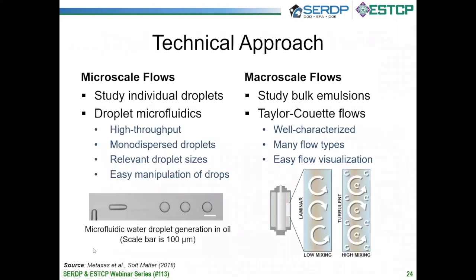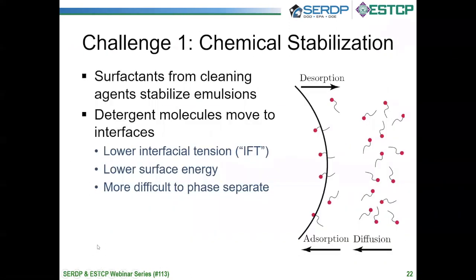So the first challenge, like I was saying, is that they're highly chemically stabilized. These waters will pick up detergents like deck cleaners, and soaps from personal care products, and these cleaners and soaps contain surface active additives called surfactants that make them such great cleaners. But these surfactants have molecular properties such that part of their molecular backbone is attracted to water and part of it is attracted to the oil phase.